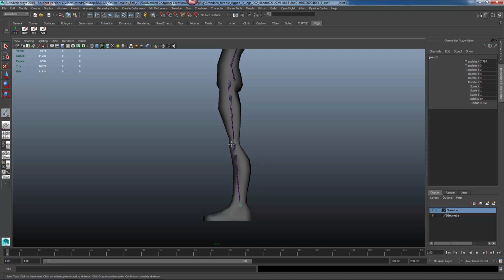If I'm not getting enough of a bend here, because it's a little more common to put a bend, I can use my pick arrows. So I'll pick walk by tapping the up arrow on my keyboard, and I could drag this by holding down my middle mouse button. It allowed me to move this while I'm still drawing it out. Okay, so I could drag it forward a little bit, and something like that would not hurt anything at all because really these are going to go off of the orientation of this joint.